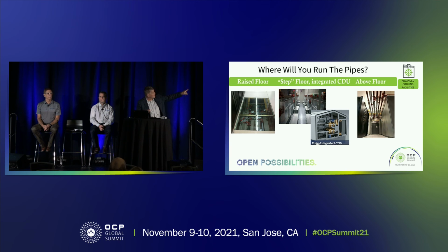You see some others, like dual phase immersion cooling in the middle there, that also integrate liquids as part of their rows of racks. And the final aspect ends up being, in some cases, neither of those work, and you have to run the pipes overhead. And so that's where you apply those principles of science, FMEA, MTBF, and MOPs and SOPs. You don't put your valves right over your rack, you don't put your strainers right over your rack. And you have liquid collection where you need liquid connection, but you don't over-design.